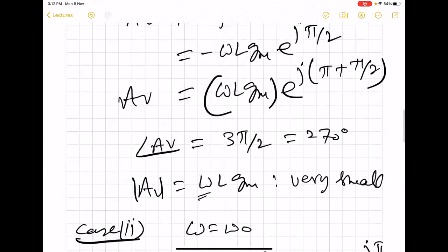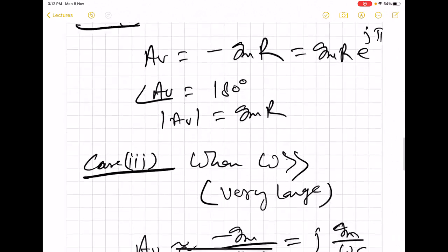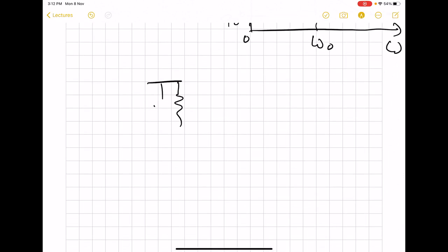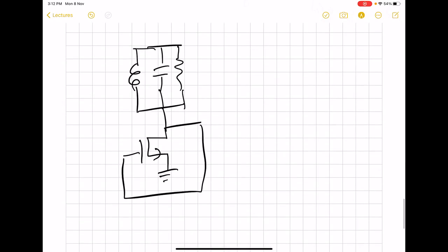If we try to make the loop using this single amplifier, we will not be able to achieve a phase shift of 360 degree, because here we can see that at max it is able to offer a phase shift of 270 degree. So we cannot make this loop and expect that there will be finite output for no input,